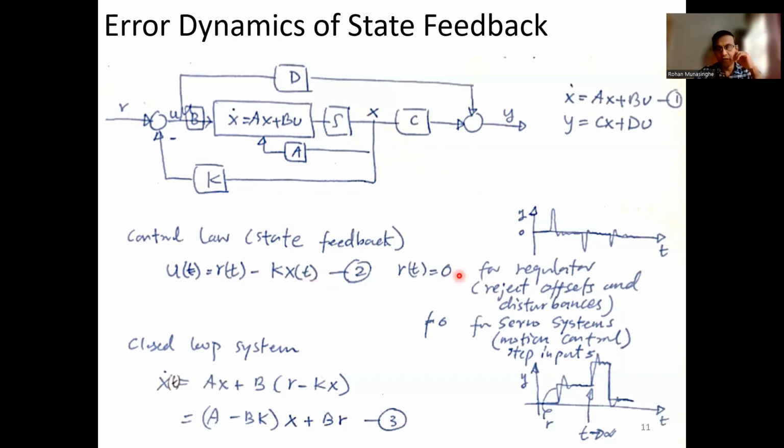All right. So it is here because even though I have already explained, maybe later you might be watching and wonder where is the reference, right? So for that reason only I have written it here. So this is basically how the whole system is written using state feedback, and eventually you get minus bkx plus br, the reference, because r is 0, don't have to worry about it.